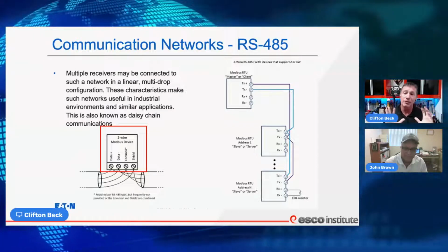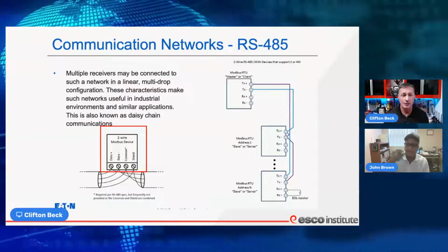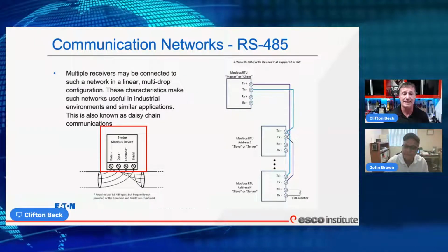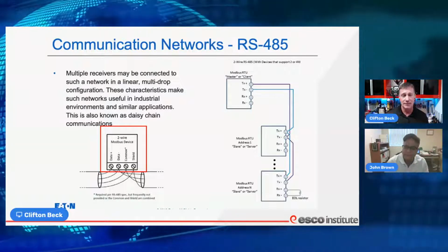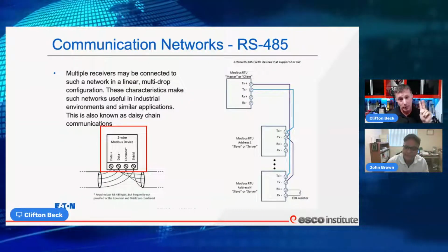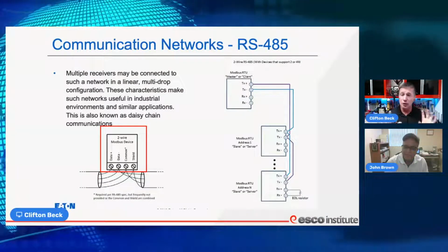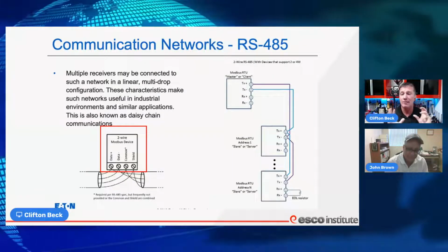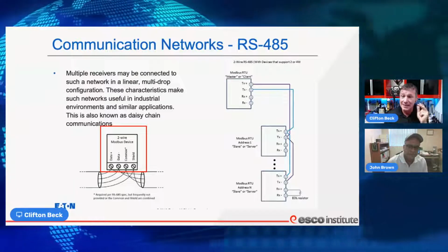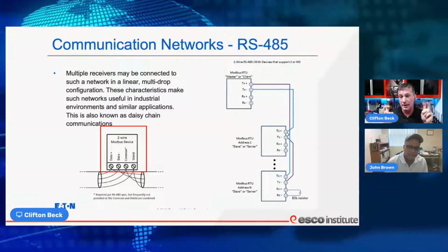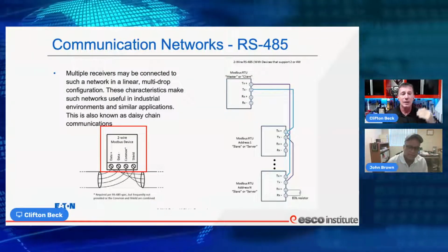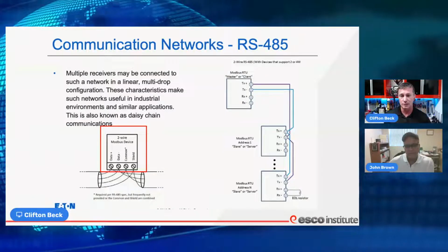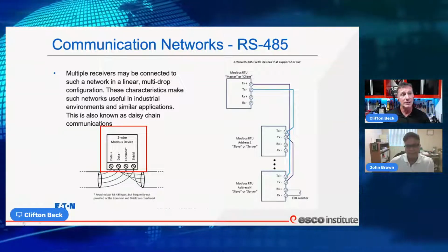If we look at this reference from Eaton, it will tell us that the RS-485 system has been around for a very long time, really developed back in the 1980s, and it's based on a 5-volt DC two-wire principle, two-wire communicating system. It could be up to 4. Most of the time we're using 2 wires to develop that 5-volt DC signal, but it is in reference to a ground or a common landed ground. And we have a positive signal that is in reference to ground and a negative signal that is in reference to ground. So how do we get to that point?